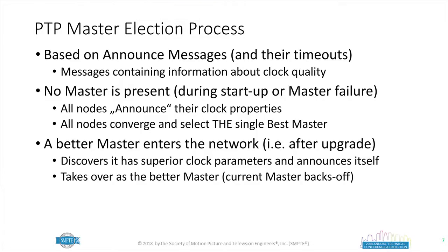The messages contain information about the clock quality. So is it locked to a specific reference? Is it locked to, as in a GPS? Is it unlocked from GPS? Is it locked to another kind of reference? This is the basis of what you use for the BMCA, the election. In case there is no master, either during startup or due to a failure, the nodes will all compare their announce capabilities. Okay, so the clock properties are reviewed, and they will all converge to select one and only one master, i.e. the Grandmaster. Okay, that's where the terminology Grandmaster comes from.